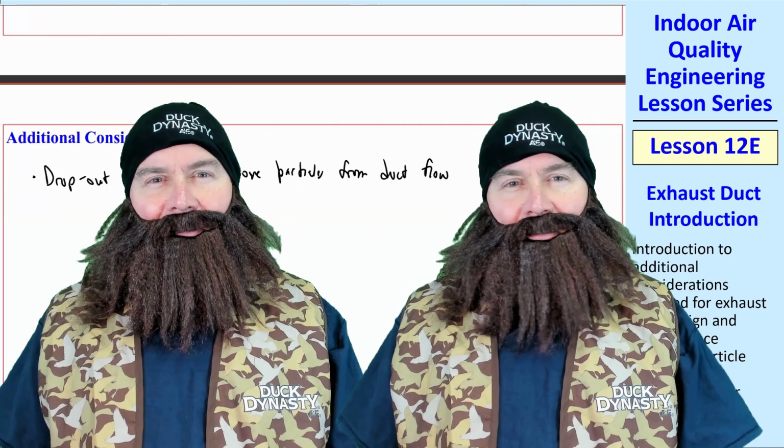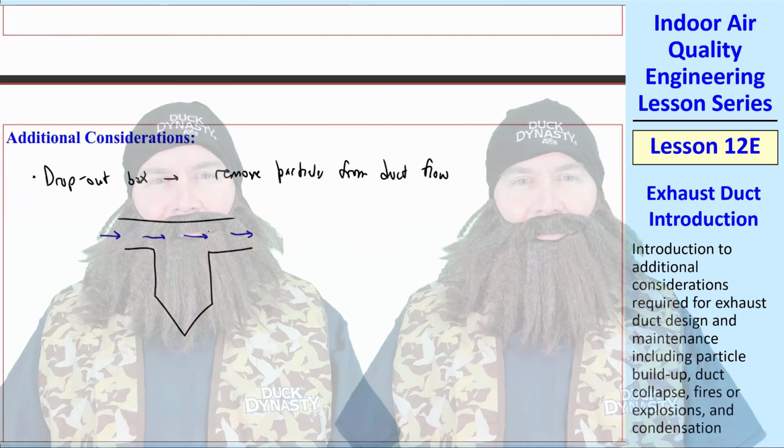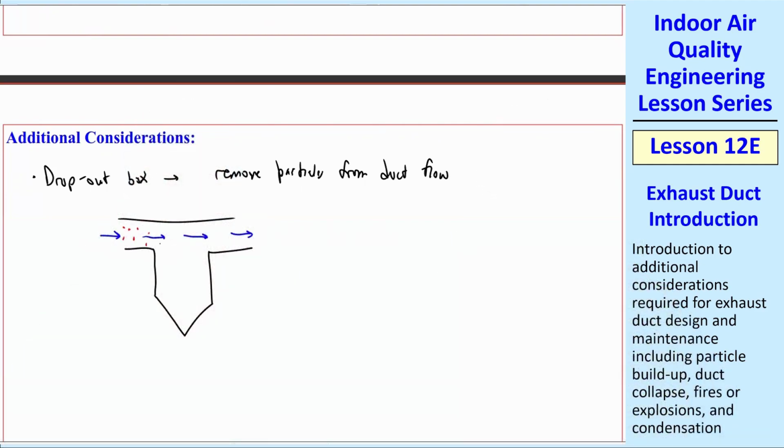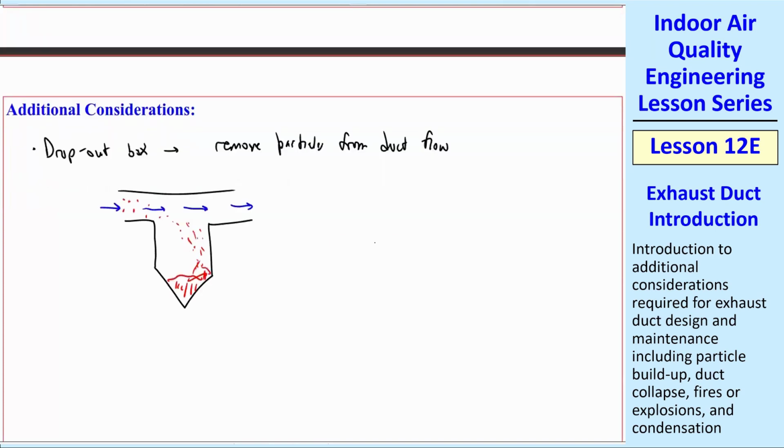Oh, right. You have the air going through, and it has particles in it. And the particles are heavier than the air, so they tend to drop down, and then they start collecting down here at the bottom of that drop box. You have to clean it out every once in a while.